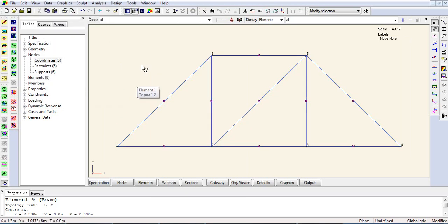The reason for this is that bar elements only carry tension and compression, so there will be no shear forces or bending moments. Meanwhile, this action effectively makes all joints free to rotate or pinned, as intended for our problem.